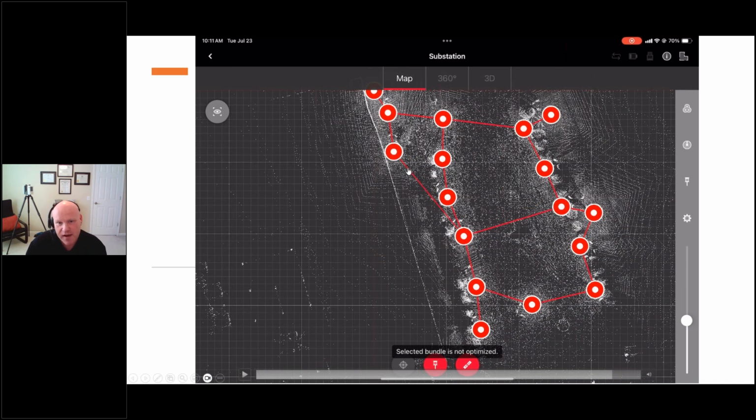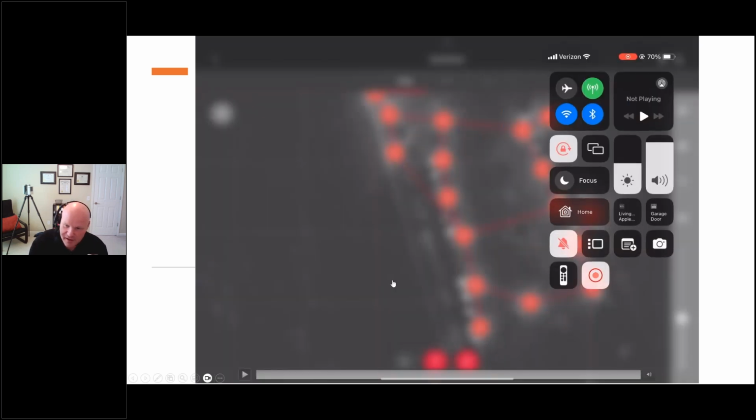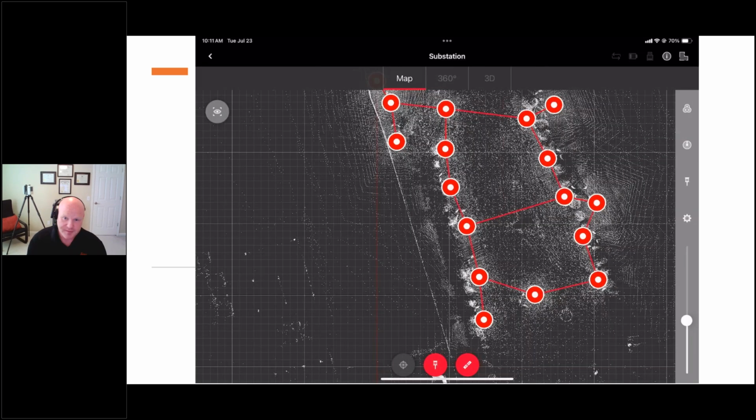So if this was scan 5 and scan 6 and they went a little too far, you see this a lot if it's like a distribution power line down through the woods and it's just a 4-wheeler path and nothing but vegetation. You can still cloud to cloud in there, say 2 centimeter accuracy overall, 2 to 3 centimeter, because you're going to see points down on the ground, but you have to tighten up your scan spacing. So if they need scan 7 to be out of sequence, back up and put it in between 5 and 6. So it'd be 5, 7, 6, 8, to bring 8 a little closer next time. So just train your crews or your scan techs that if the scan jumps, you need an additional scan. That's really the point I try to drive home there.